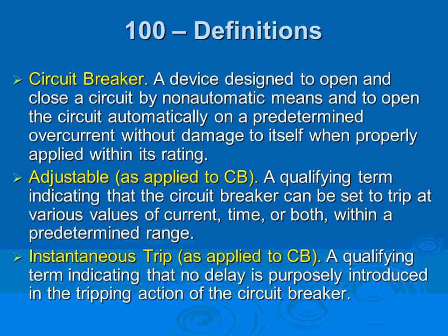How many of you have heard of a motor circuit protector? I'm sure Jeff yesterday talked about the motor circuit protector. When you have motors, you have your disconnect, and then you have to have your overload component, which is a fuse or circuit breaker. Then you have to have your controller and overload, right? So instead of having a circuit breaker, they have a motor circuit protector, which is just looking at the short circuit, not the overload. Why is the overload not an issue on the motor? Because you already have an overload component. So that's coming on motors, that they use an instantaneous trip only circuit breaker.